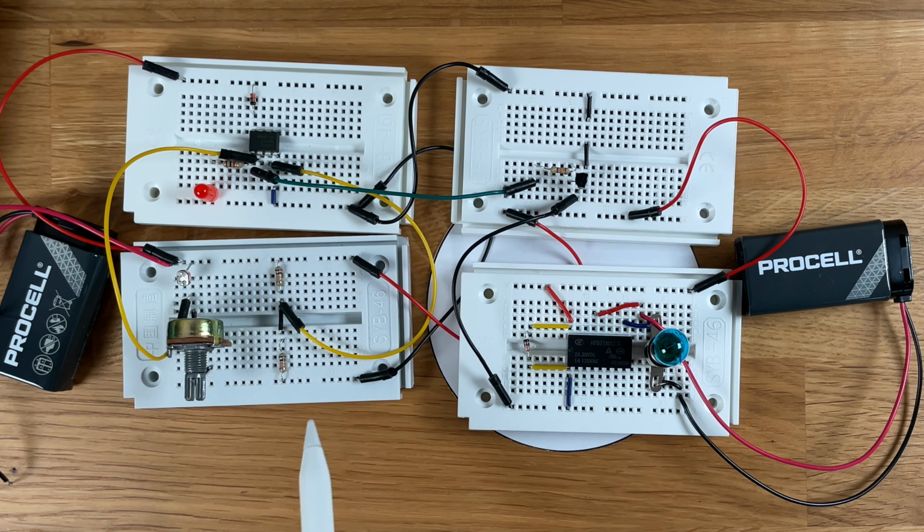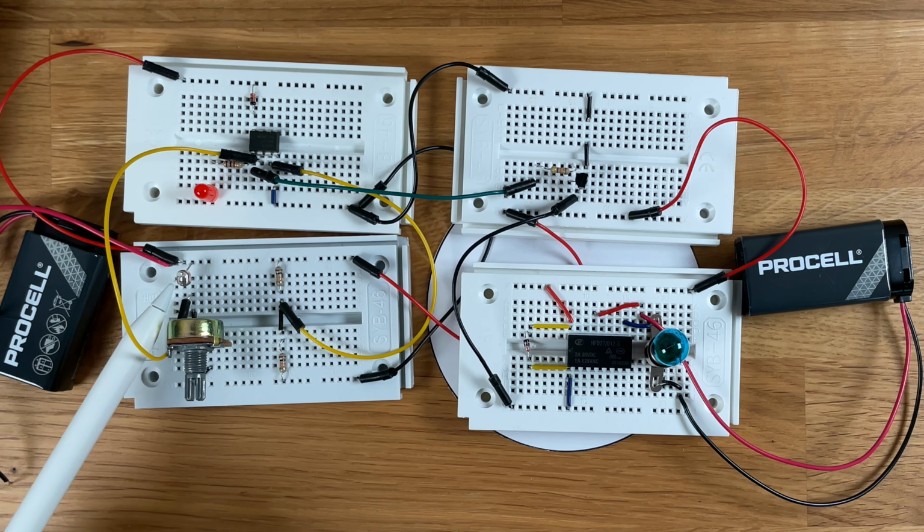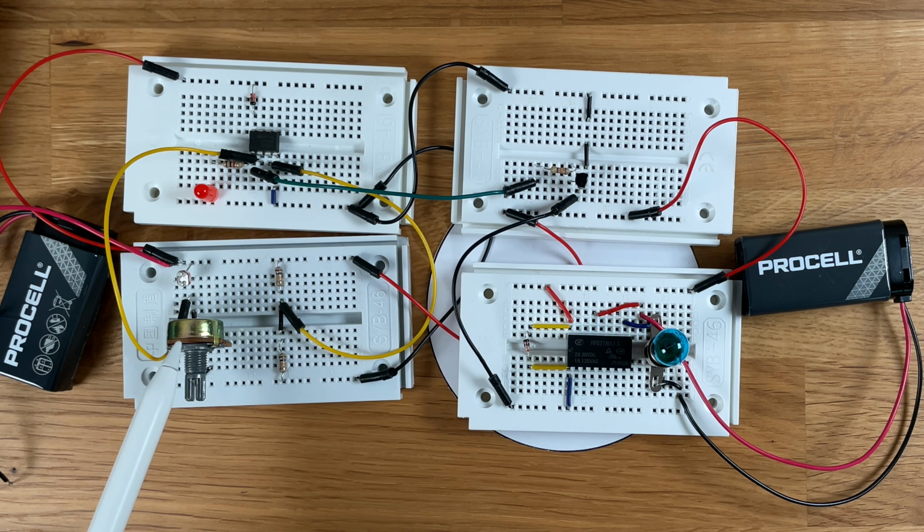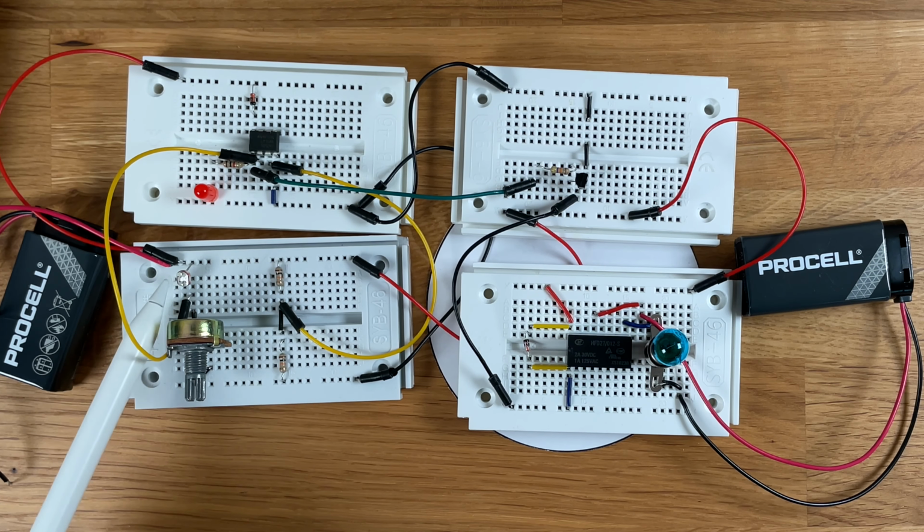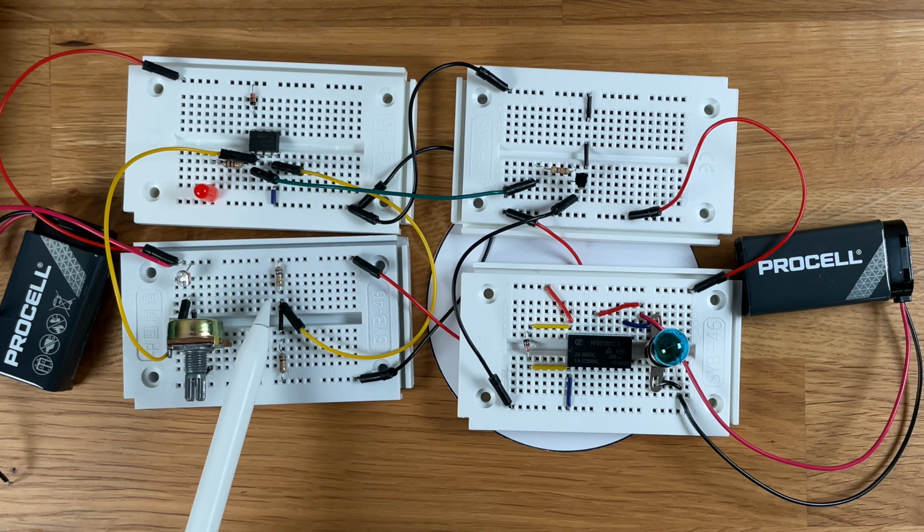So the first breadboard here contains, and there's an individual video on this breadboard here, the light-dependent resistor, and the potentiometer, which is used to balance the voltage in between these two. So we have one point here in between, which is driven by a voltage split between the reference value here adjusted by the potentiometer and the resistance value which is directly related to the ambient light falling onto this surface here. And this reference point is compared against the reference voltage in between these two fixed value resistors here.